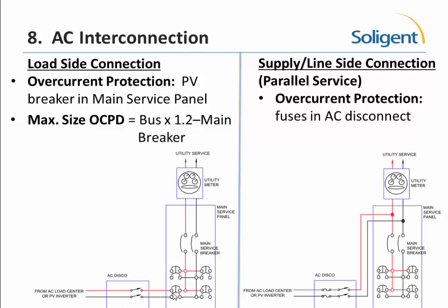In this case, because we have fusing here, our breakers right here are considered fusing, so we don't need to have a fused disconnect. All we have to do is disconnect it. Some jurisdictions really want this. Some say this breaker is good enough. Tough to say, depends where you are. The fusing is there not to protect this device or anything downstream, our inverter or anything else.